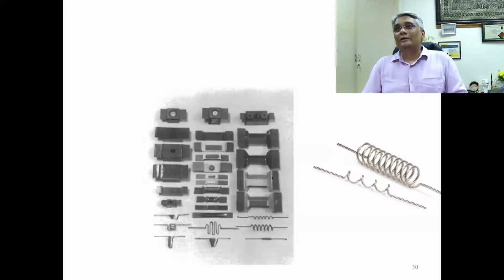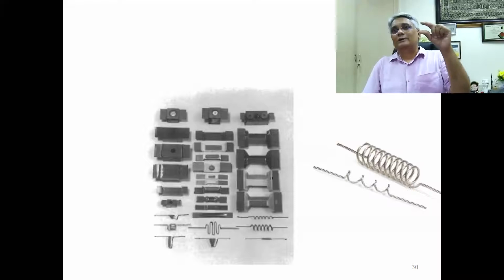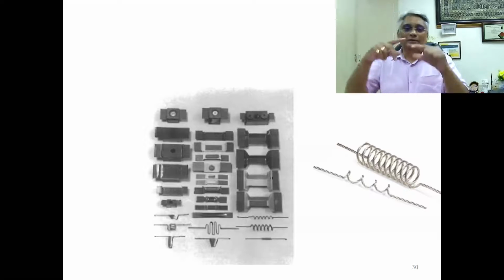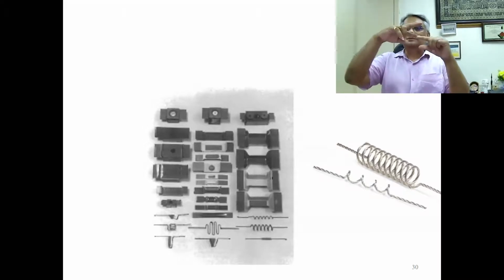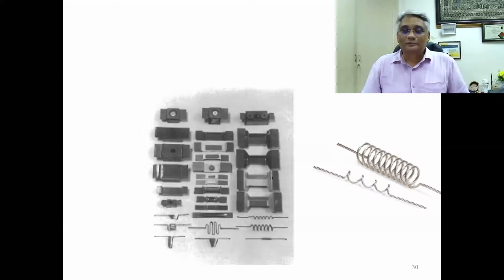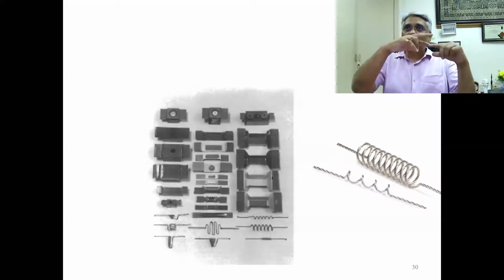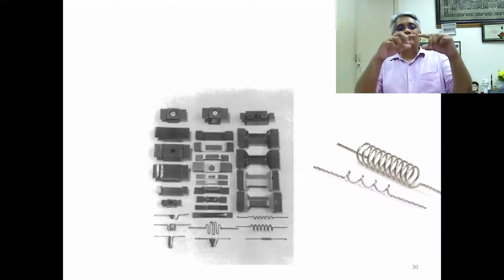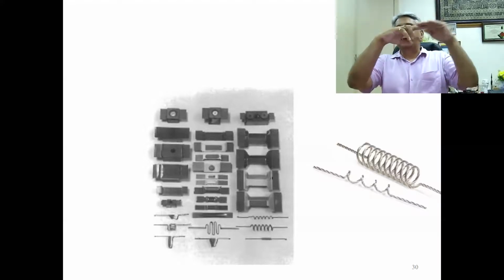But what is happening in that process? So now you can imagine this is a 1 inch winding. Now you start there, and this is a substrate. So we always want to keep the distance between the source and the substrate constant, right? You don't want to vary that, because this determines your deposition rate. Now what is happening, of course, your substrate is fixed.